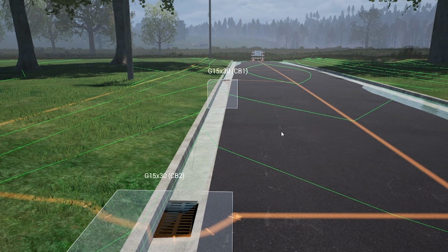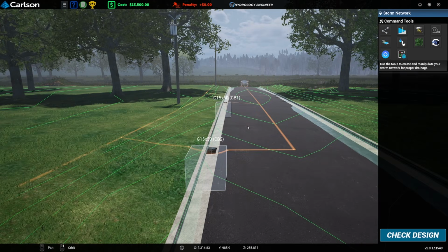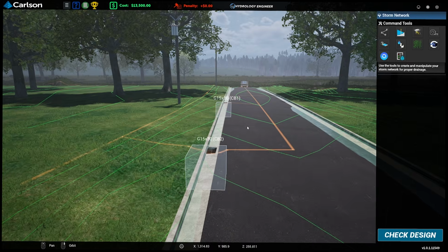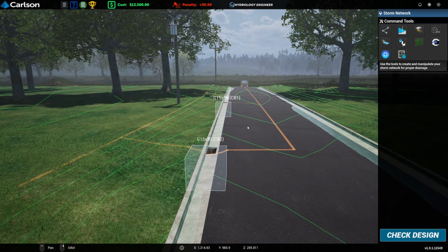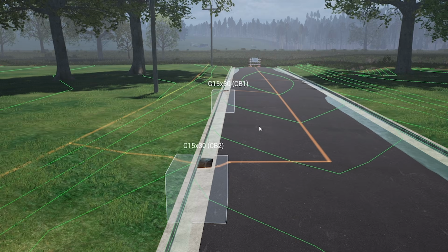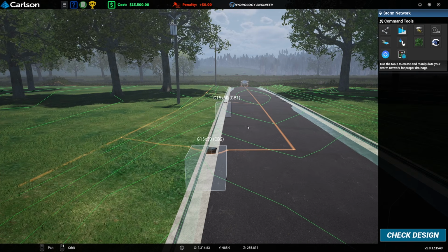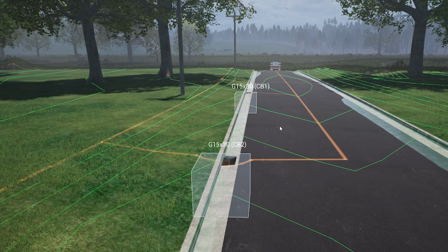So from this curb into the road, the water can go 1.2 meters, and this is simulating like the worst storm possible. So I think when we do gullies, is it a 1 in 30 year storm or a 1 in 5 year storm? Basically the worst storm that's likely to appear once every 30 years or once every 5 years. I literally can't remember. It's been quite a few years since I've done actual drainage, and of course the standards change all the time, so my knowledge may be slightly out of date.